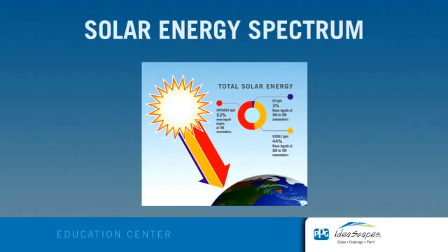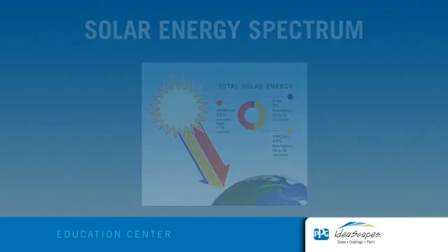Solar infrared is commonly referred to as shortwave infrared. Heat radiating off of warm objects has higher wavelengths than the sun and is referred to as long-wave infrared. Low-E coatings have been developed to minimize the amount of ultraviolet and infrared light that can pass through glass without compromising the amount of visible light that is transmitted.